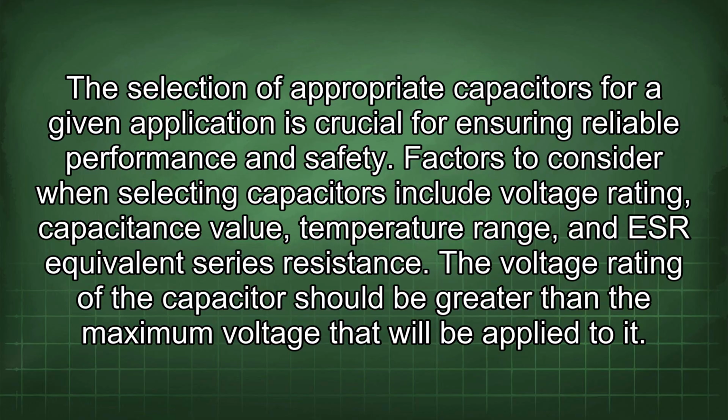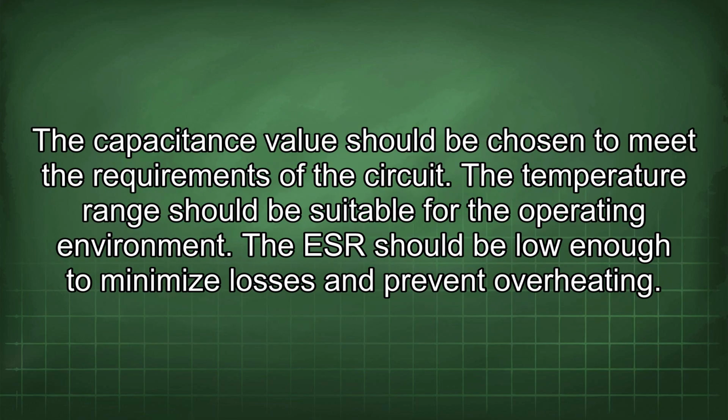The selection of appropriate capacitors for a given application is crucial for ensuring reliable performance and safety. Factors to consider when selecting capacitors include voltage rating, capacitance value, temperature range, and ESR, equivalent series resistance. The voltage rating of the capacitor should be greater than the maximum voltage that will be applied to it. The capacitance value should be chosen to meet the requirements of the circuit. The temperature range should be suitable for the operating environment. The ESR should be low enough to minimize losses and prevent overheating.